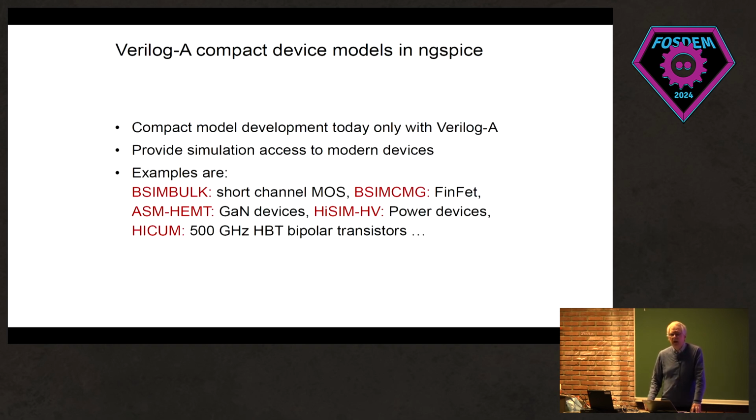We allow Verilog-A compact device models in NGspice. Compact device models are the model equations describing modern transistors, for example. These complex, tiny things like FinFETs would have 500 parameters and lots of differential equations to describe, and people do the development in Verilog-A.